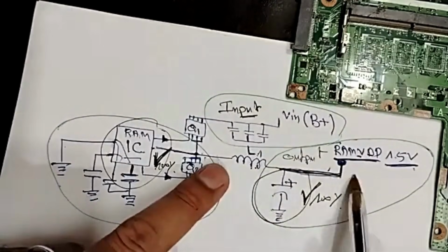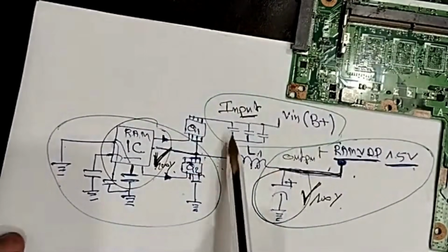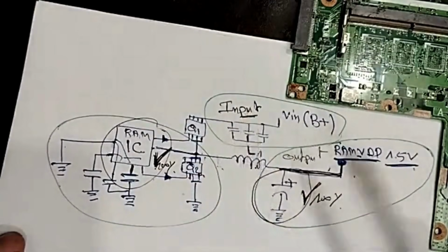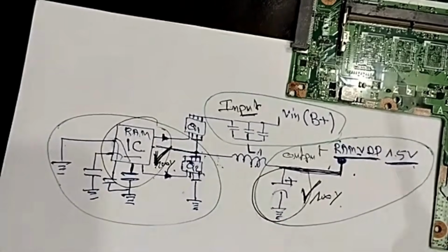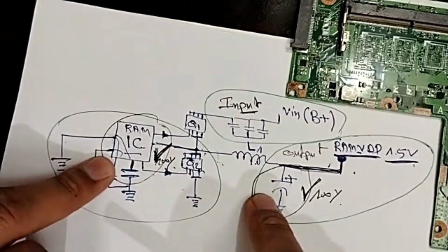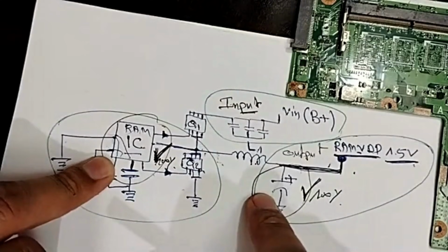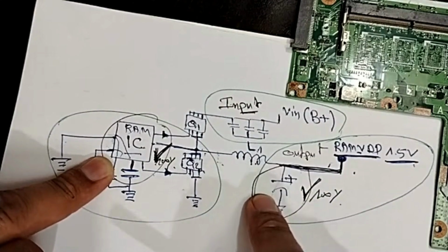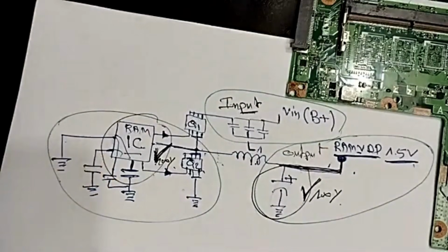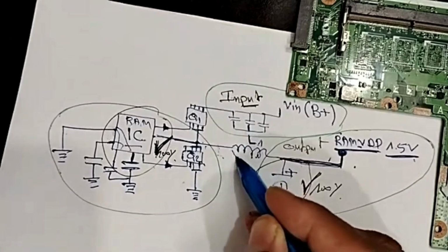Guys, for this kind, we have three parts here. The short could be here in the input, could be in the output or in the side. How do we deal with this kind of short circuit? Please, now we are in the deep work. Please, attention, my friends. If you have a short, my friends, without thermal camera, without voltage injector, remove the inductor.